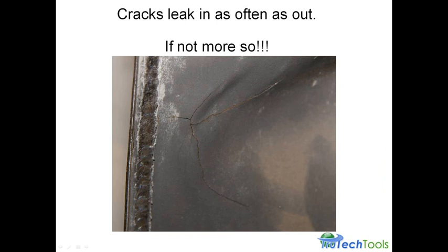And everybody says, well, you got a draft inducer motor on there, so it's going to suck air and it's not going to let CO out, right? And you think, well, heck, that's not a problem. Well, it absolutely is. It's a huge problem, because if you remember the earlier slide, we talked about secondary air, and that secondary air is drawn in by the burner. So it's drawn in at the point of combustion.